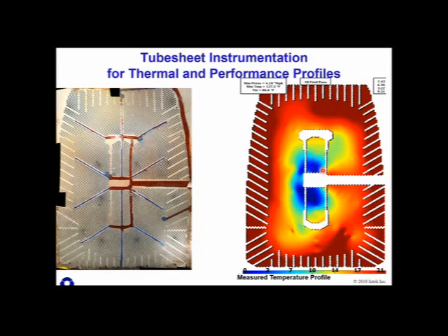We've got a stagnant zone here in the air cooler section, a stagnant zone there in the air cooler section. This particular condenser, if you haven't guessed already, has a solid baffle here, being the boundary of the left boundary of the air cooler section, and a solid baffle here and here. And then the gases draw off from a pipe that reaches in here this way. So this is the air cooler, 2 air coolers per bundle. This is a stagnant zone. This is an airbound zone, right? This is outside the air cooler. It's a region where air goes and dead ends. And so these tubes are all affected by air binding.